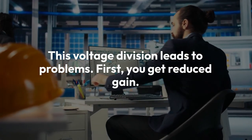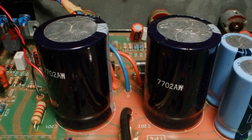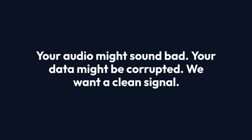First, you get reduced gain. The signal going into the second stage is smaller. So the overall amplification is less than expected. Second, you might get distortion. If the op-amp is forced to supply too much current, it might not operate linearly. The output waveform can become clipped or distorted. Your audio might sound bad. Your data might be corrupted. We want a clean signal.